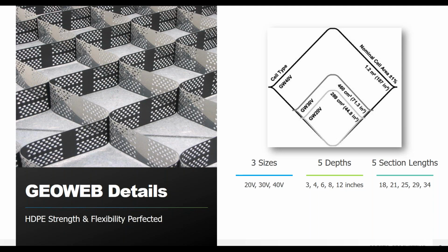And so another thing I want to point out is going to be the ultrasonically welded seam. And this is where all of the connecting points are. This is a very important aspect about how the GeoCells function. The stronger the seam strength, the better the performance of the GeoCell overall. A strong seam allows for the use of heavier infill materials, the ability to be placed on steeper and taller slopes, and better overall lifetime performance.